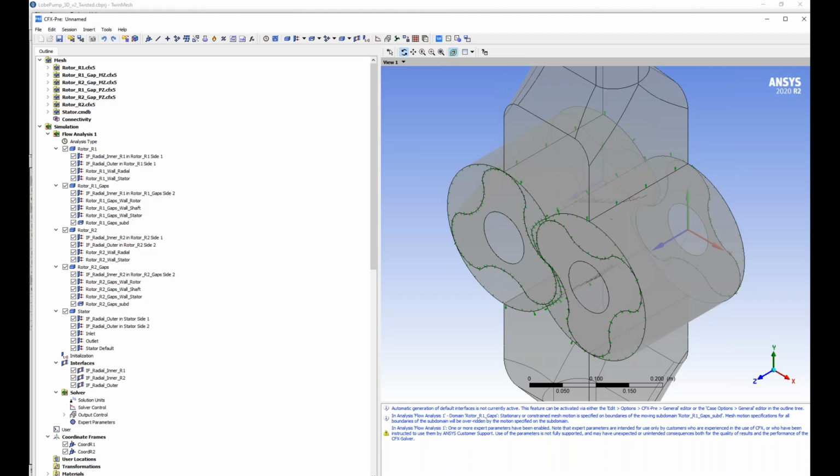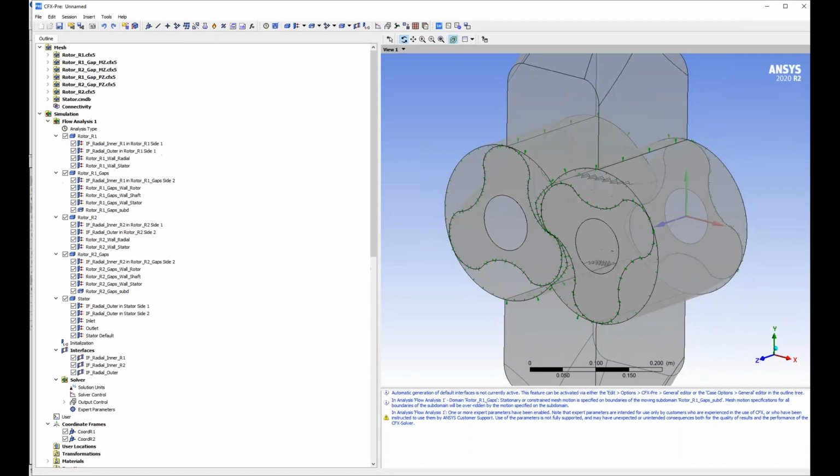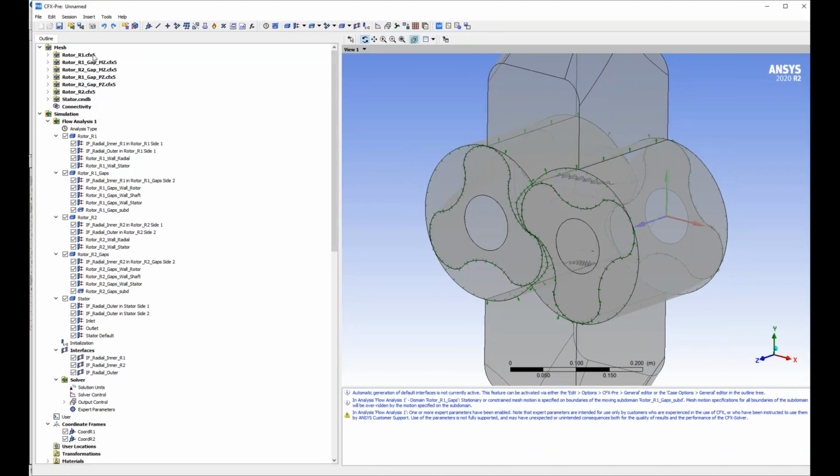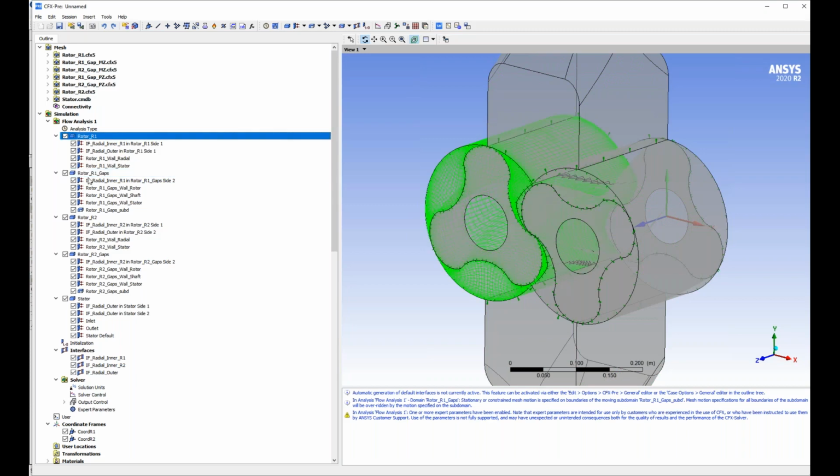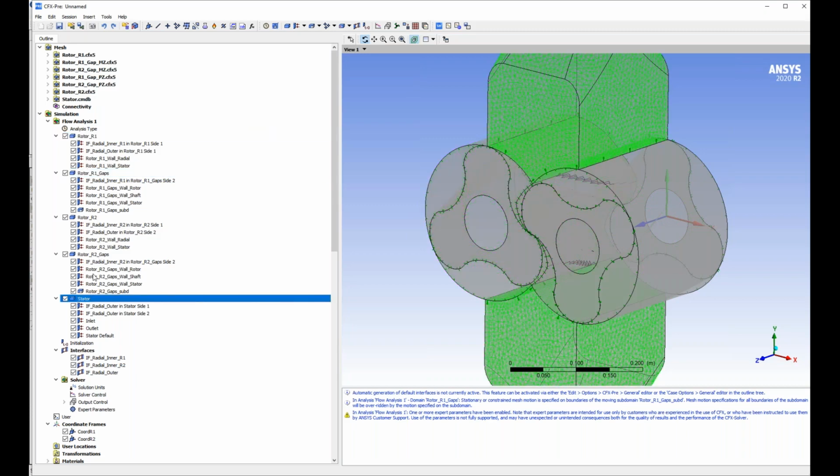And in the background, it will load the grids from TwinMesh for the initial position and also the mesh coming from ANSYS meshing. And it will assemble the setup for us because TwinMesh knows what machine type this is. We specified the operating point, and once it's finished, we see that the model is imported. If you are familiar with CFX, this setup might be familiar to you. So we have all the meshes on the top, then we have the domains, so rotating domains and the stator domain, and all the boundary conditions which we need to run the simulation.